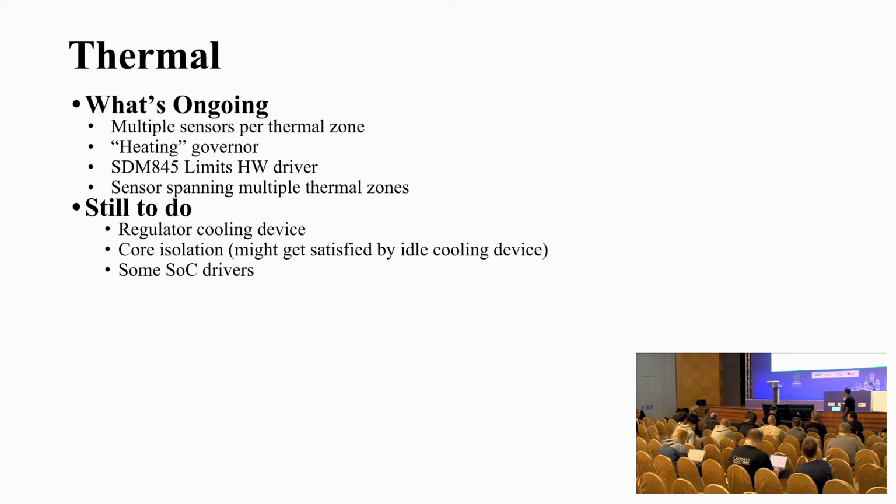So it's something I started looking at, and I'm now in touch with the team inside Qualcomm that's in charge of that. Back when we upstreamed the T-Sense support, the IRQ support was missing in the thermal framework itself. It supported only polling, and then moving to interrupt based. So it's possible now.